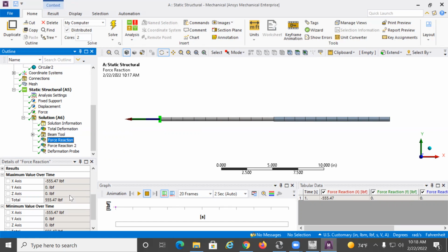Yes. When we're using the finite element method, it's a numerical method. There are approximations that are undertaken, and with all the numerical manipulations that are being done, this mathematical error may increase, but we want to make sure that it is within acceptable limits. In other words, that we have a fine enough mesh to the extent that the solution is converging, getting as close as possible to the exact solution.